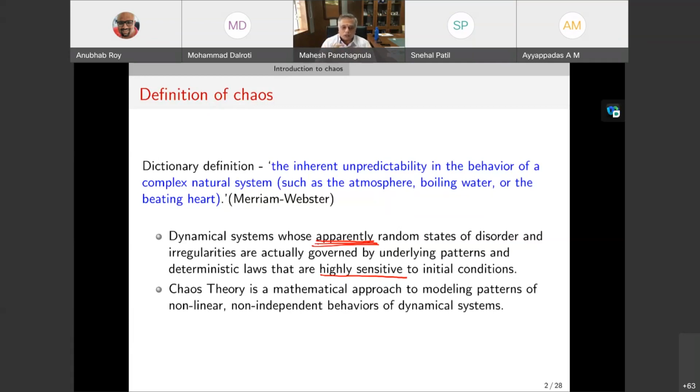Because every little rotation of the coin, and what the coin does when it hits the ground, can be determined. Let's say I knew the coefficient of restitution between the coin material and the ground, and I know the initial velocity and angular velocity prior to impact. From the coefficient of restitution, I know the conditions after impact.